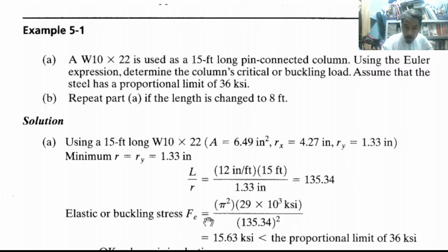Okay. So use this value in our determination of Euler buckling stress. So what is the value? 15.63. This 15.63 stress is less than the 36, no?